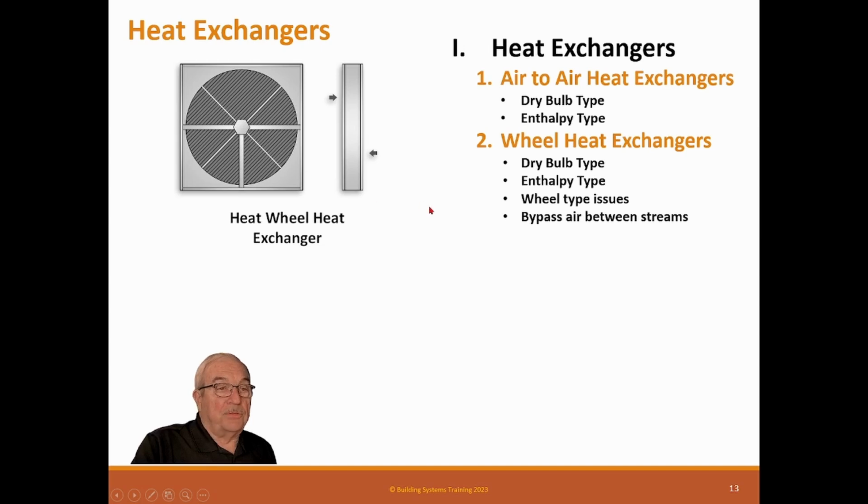Bypass air between streams. So now this one here, that other heat exchanger, it's tightly sealed between them. It never transfers air between them, and that one can be used on contaminated air. This one should not be.